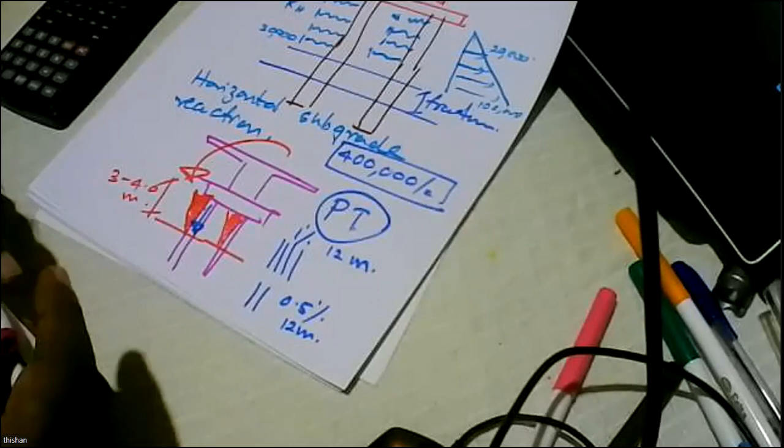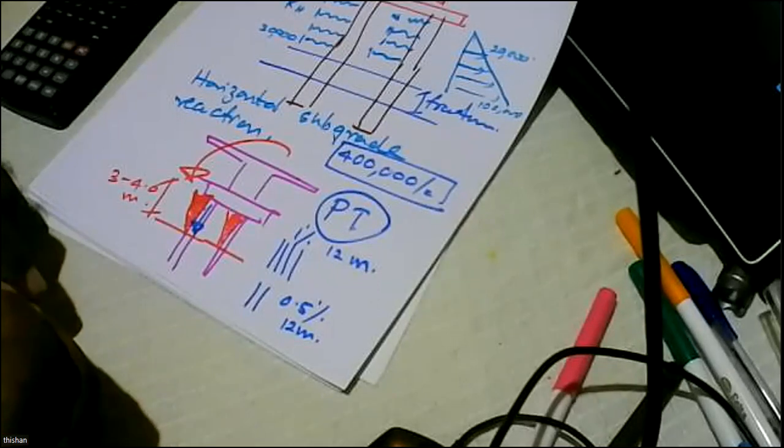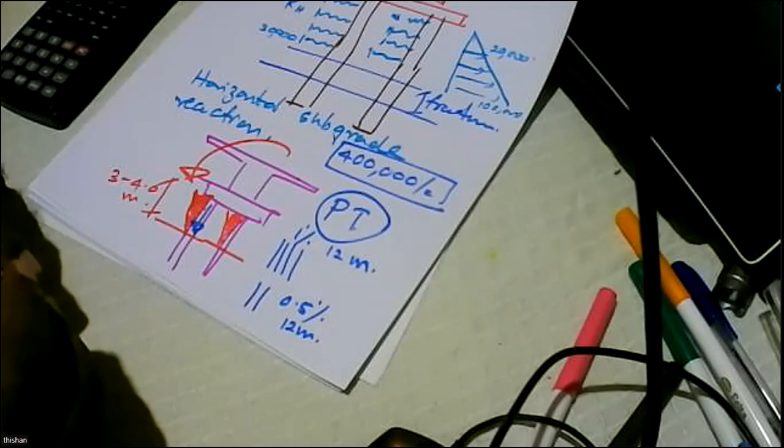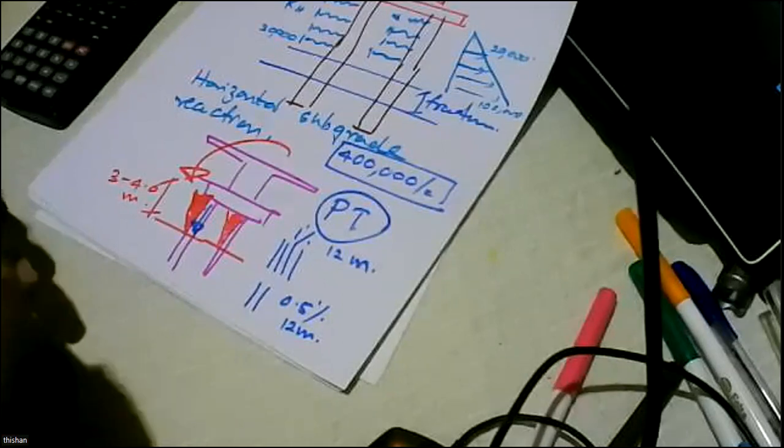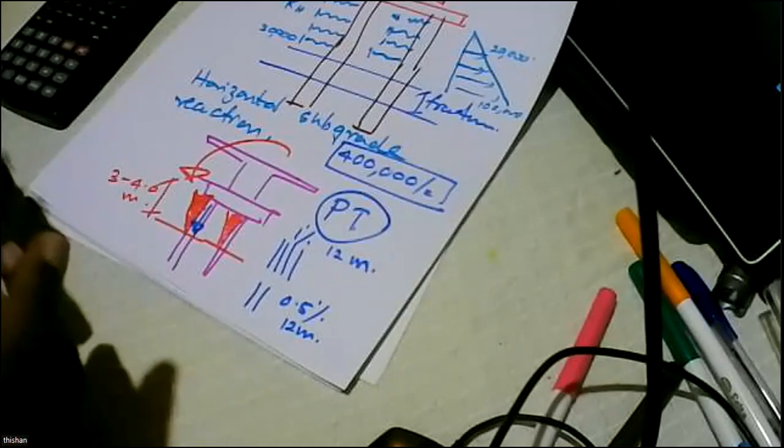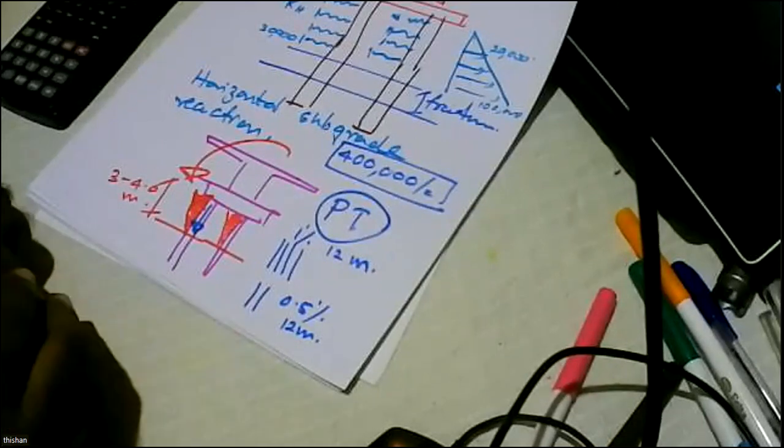A lot of engineers put a lot of reinforcement into the pile even going into the bedrock. But very capable engineers have designed a lot of pile foundations where they have omitted the reinforcement, showing that the pile is not subjected to any bending moment.